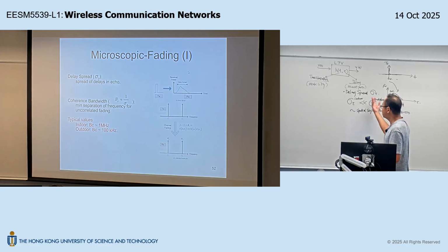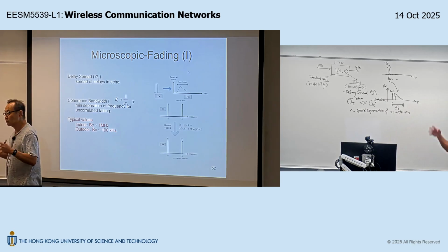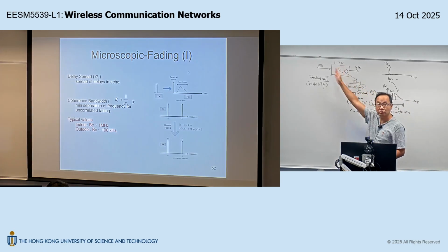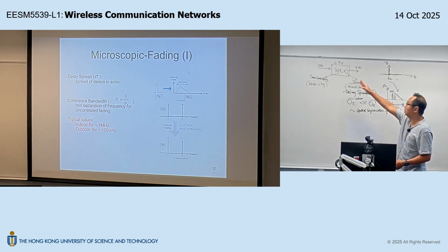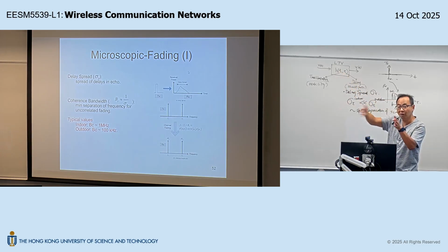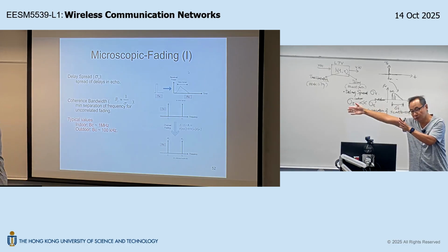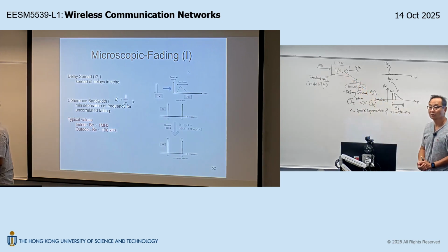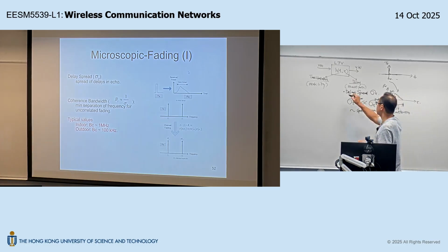So this number is much easier to measure. And measuring this number gives you some statistical properties of the two-dimensional impulse response. So if you have a large delay spread, you expect this impulse response in the tau dimension will have a longer tail, longer memory. Okay? You transmit an impulse, you see a lot of response extending over a large delay. Is that okay? All right, so this is delay spread, which is one parameter.